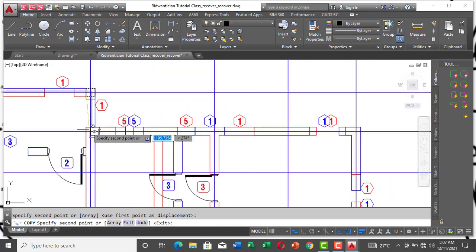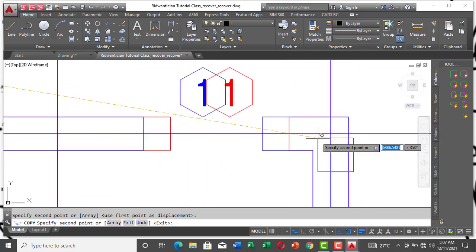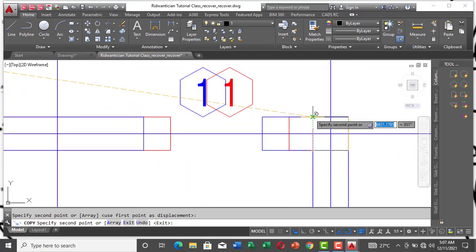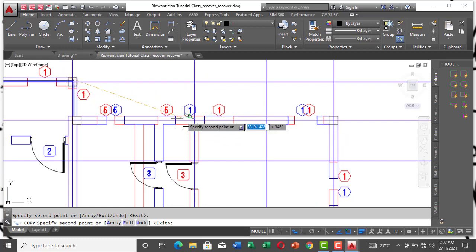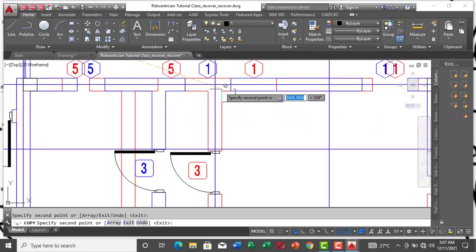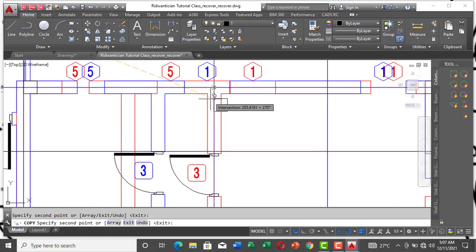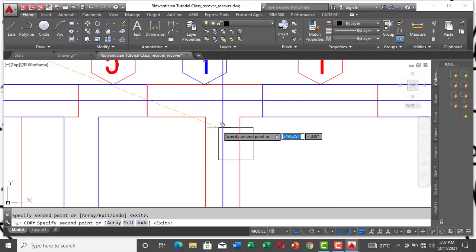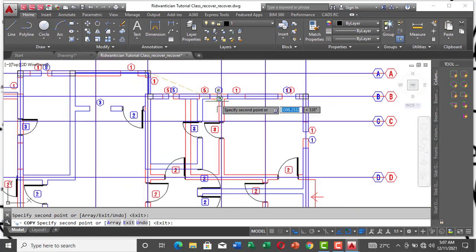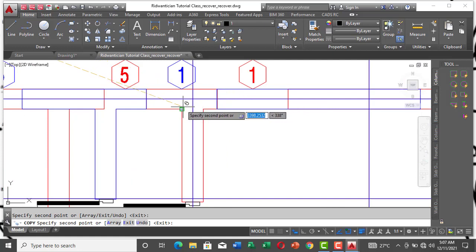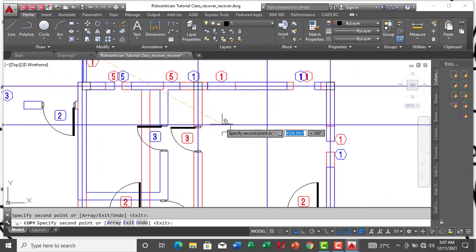So I have a column there, and then at the last edge here too I have a column that will work for both stories, and then in between and here you can put a column. So if I put a column here, the column will not be able to go up to the ground floor. Here you can see, it will work for the first floor perfectly, but for the ground floor, no. Let me put the column here. So this column is not going up, because you have a window here, so you have to be careful. Okay, so that's good enough for the ground floor.